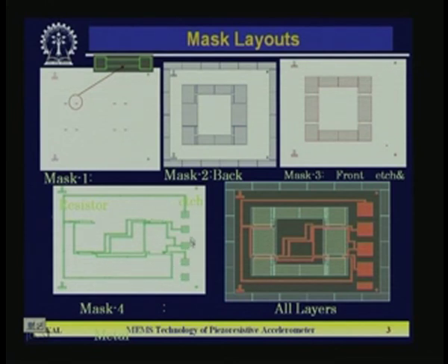And these are the interconnection layers. Because in the Wheatstone bridge we have seen there are 8 resistances, you have to connect the 8 resistances such that you can get very low off-axis sensitivity. Here the resistance lines move from one end of the frame to the other end of the frame, and the lines are routed in such a fashion that there is no overlap. So we have not used any underpass resistances here, and we have used a single level of metallization. Some tricks you have to follow so that the metal lines move in such a fashion that 2 lines will not touch each other or overlap.